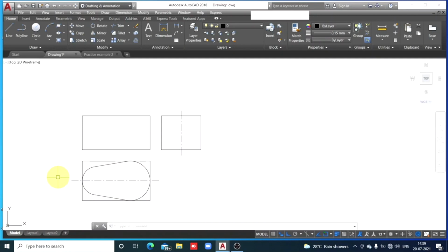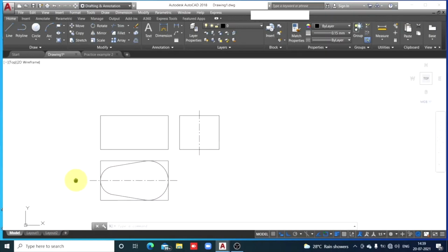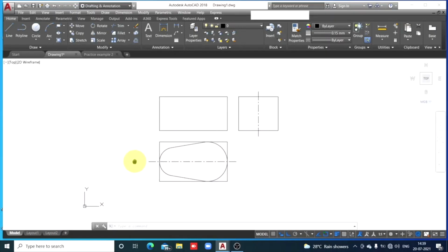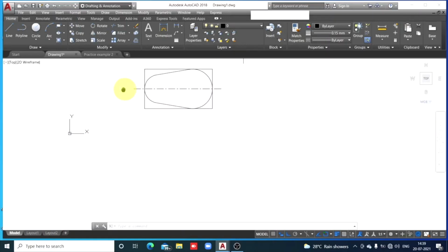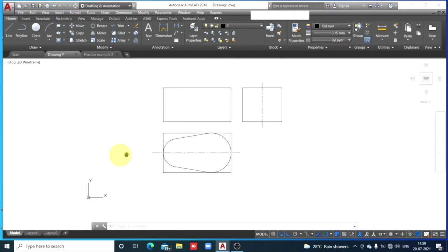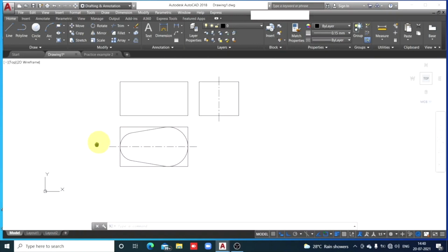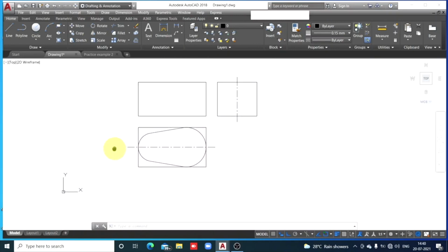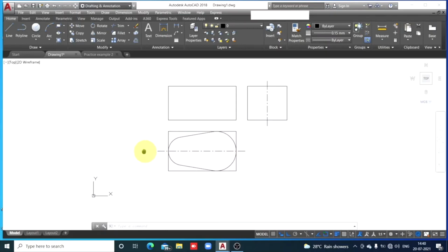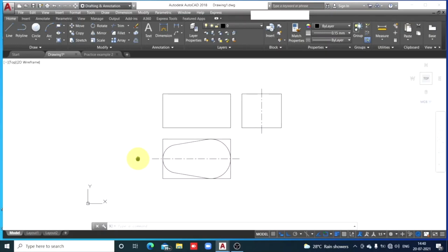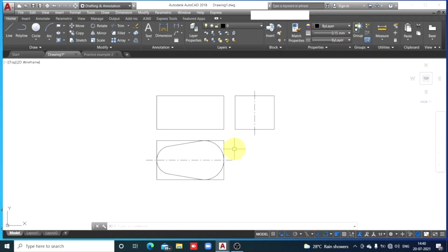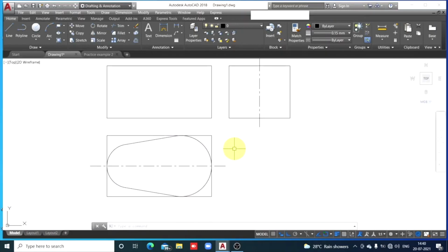You can bring this drawing to the center. How? Press and hold the wheel on the mouse and move the drawing in this way. The wheel on the mouse is still pressed. Check shape of the cursor has changed. And wherever you want that drawing, so I have centered it, leave the mouse wheel. So this is how we have centered the drawing again. By rotating the wheel on the mouse, you can zoom in and zoom out if required.